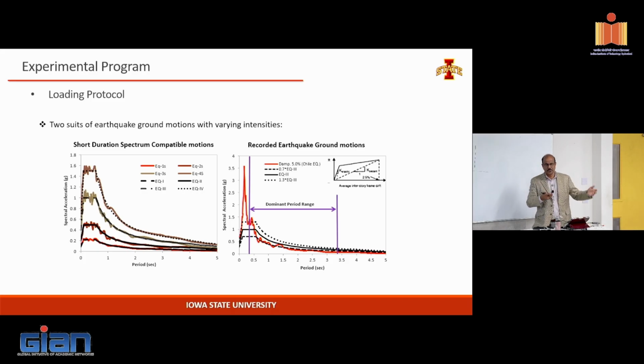So we target, say, 2% drift, do we get 2% drift? Things like that we can learn. The other one gives you the unexpected motion that will have an unexpected peak or a cycle, how well the structure will perform. So if you're running analysis, you should kind of look at both sides of it rather than just using one set of analysis.